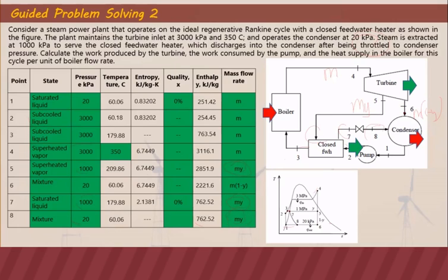For the condenser, as you can see here, the entrance of the condenser is our My and M(1 minus Y). So when you add that, My plus M(1 minus Y), the result will become M. So at point 1, it will become M. And then if pumped to point 2, that's still M. Since 2 will not mix with 5 at the closed feed water heater, 2 will just become the same mass flow rate as 3, so that's M. And there's no branching here, so that's still M at 4.